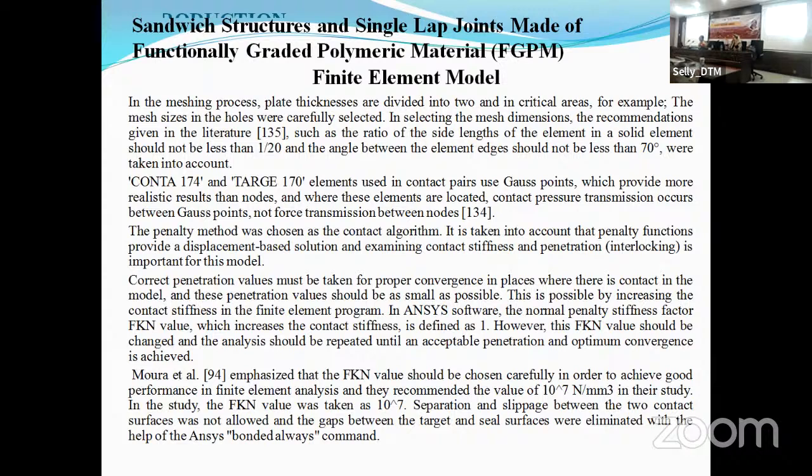In a contact model, the penetration should be as small as possible. This is only possible by increasing the contact stiffness in the finite element analysis. Its default is 1. In ANSYS, its default is 1, but it should not be 1 because